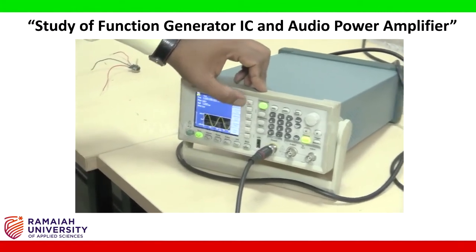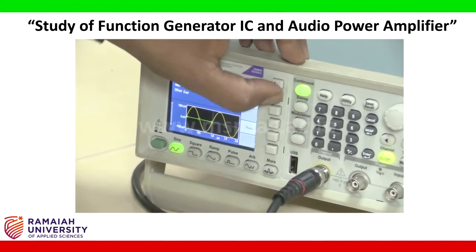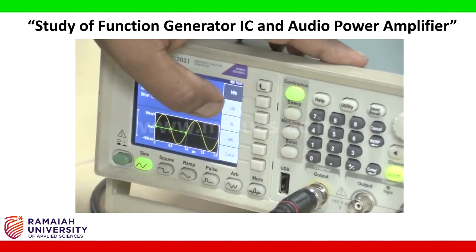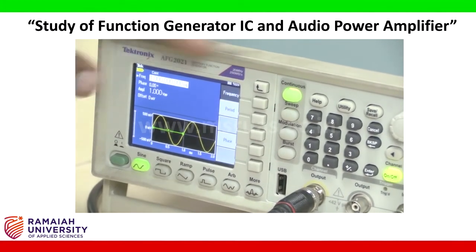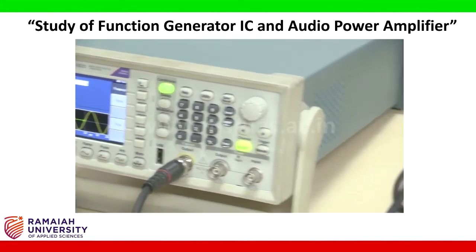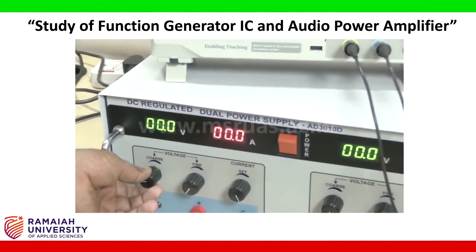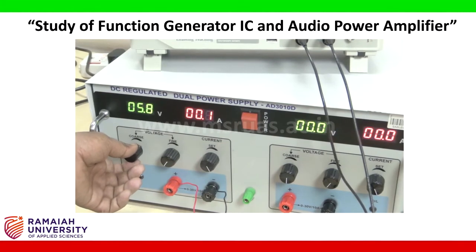Set the frequency to 1 kilohertz. Increase the amplitude to some 5-6 volt.